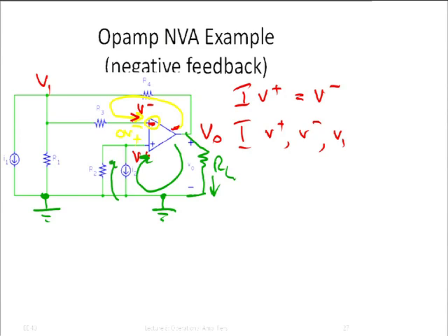Yeah? There's no current flowing back. This one goes to the ground. Exactly. The current will disappear into ground. Why? Well, because ground is a zero impedance node, right? It's tied solid through a 0 ohm resistor to the negative terminal of the supply. The current isn't crazy. Electrons are just like students. They don't put up a lot of work if they don't have to. Right? If there is a path of 0 resistance, they're going to take it. So this current all is going to disappear here. None of it is going to make it back up here.